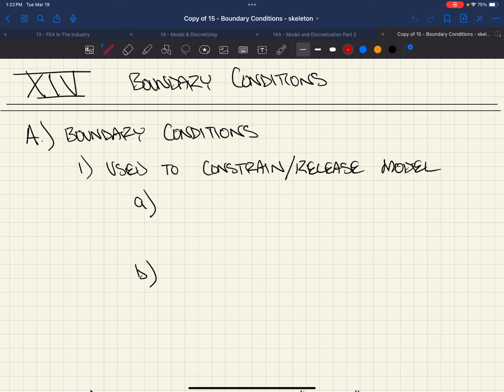And it's really cool to see that in one direction, those plates have actually buckled. Not a significant amount, but they've pushed away from the roof or the ceiling insulation. And in the opposite direction, they're tight, right? Tight to the ceiling. And so after somebody went in there and sawed out the temporary supports for the field house, everything settled into place. And luckily those bands were there, because when it did settle, it twisted, and it decided to twist in one direction for one reason or another. And so one direction is tight and the other one's buckled.